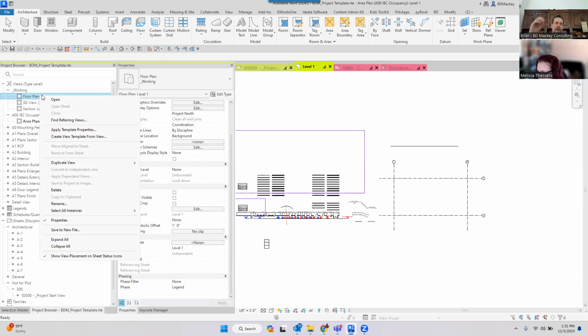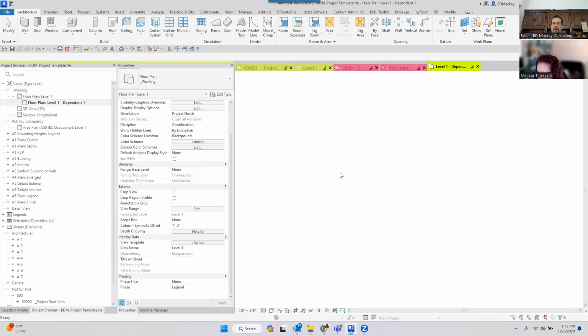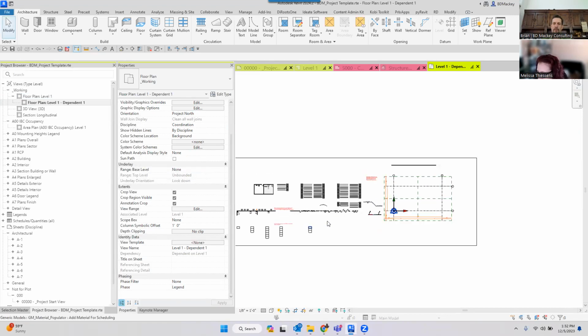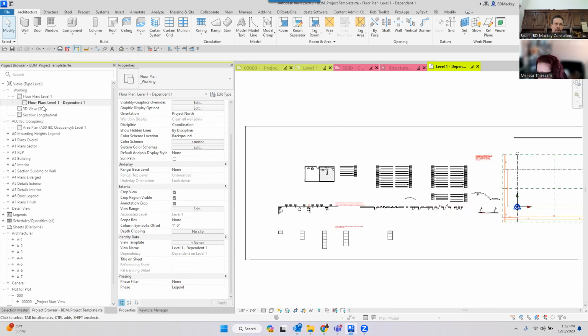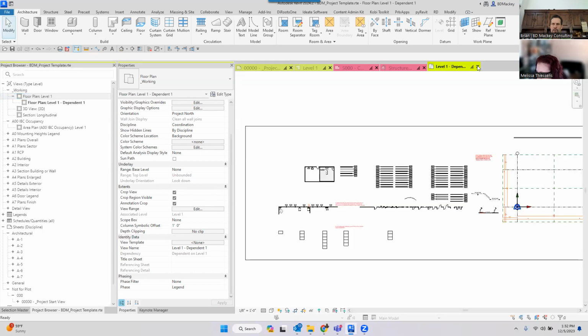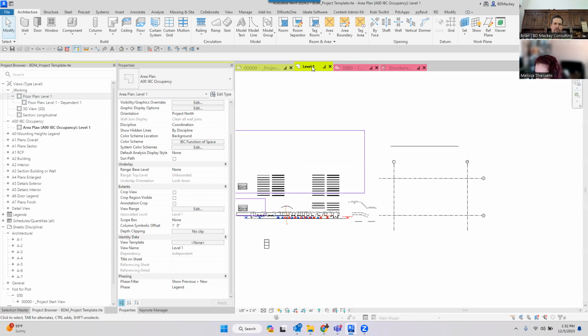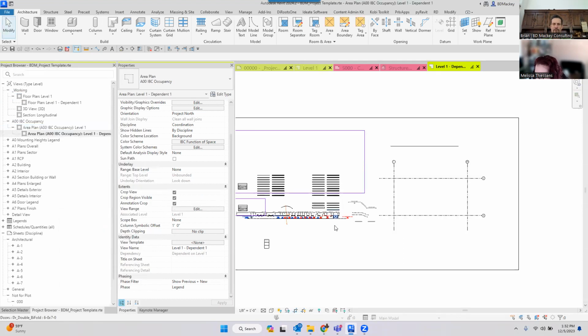So honestly, after I have dependent views, duplicate as dependent, I personally convert them all to be independent views. So I start off with views possibly dependent, and then I come back and make them independent. So if we come back here, did I delete my dimension in that parent view, or did I do that in a different view? I did it in a different view. Well, which view was I in? We should make the view I was in independent. I was in a code plan. Cool. We're going to make this one a dependent view so we can have the dimensions already set there.